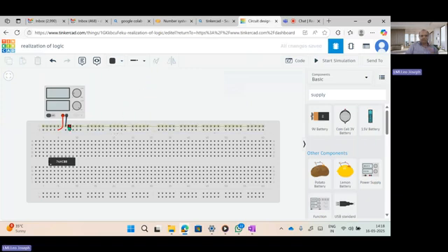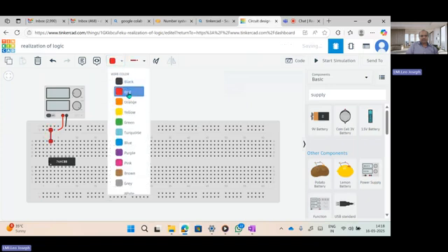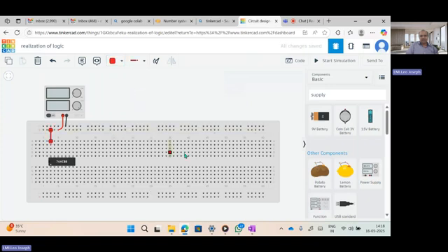So what I am doing here is, from here I can directly join these wires. This is the 14th pin, right? So the 14th pin is the power pin. So I can directly join this to here, and I am changing this wire. This is optional, I am doing it for my understanding. So better I can short these two terminals so that the connection will be easy for me. So I am shorting this wire and this wire.